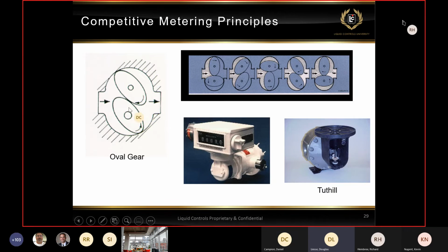Because what we're not really showing here is on the oval gear, and the second one, there are teeth cut into the outer edges of that gear, and they mesh right there in the middle. And what the product does is as it comes in from the left, it's separated to either go upwards or downwards, and it takes the path around the outside of those rotors.